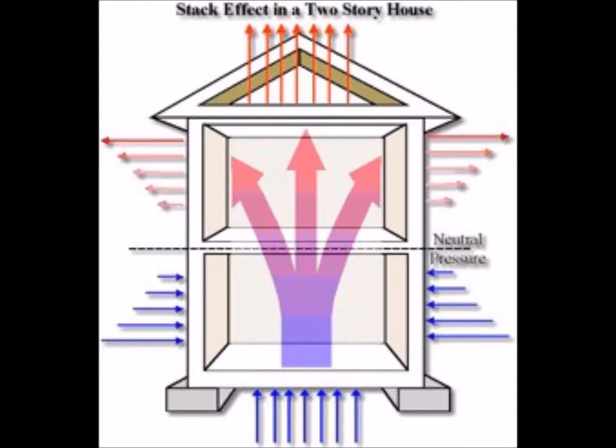For those of you that haven't quite made the investment into a blower door, there's still some valuable information and steps that you can take to depressurize the home and help those leaks stand out. Number 1, turn off the furnace. Ideally, the weather would be cool and windy out. Number 2, shut all windows and doors.